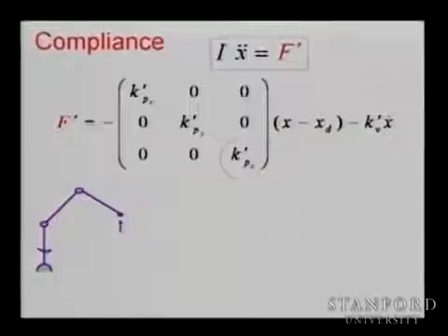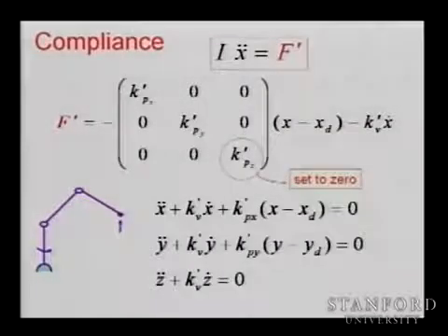I'm sorry? Doesn't it just stay where? Well, if it is 0, it is basically free now. That spring is cut, so you move it, it's going to move. So from the control we developed for the position, because we have a control in x, y, and z in task space, the end effector is stiff in this direction, stiff in that direction. In this direction, if you change kp and make it 0, now it's free. And just by making kp equal to 0, you are going to have those relations.